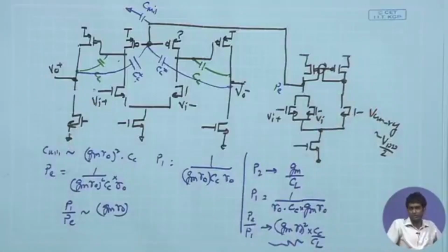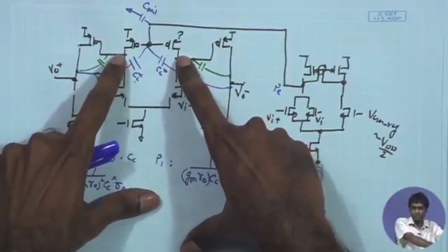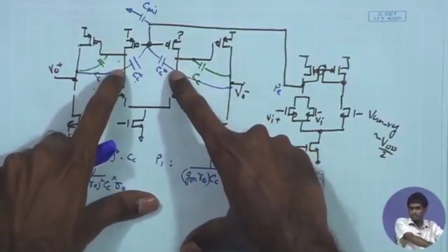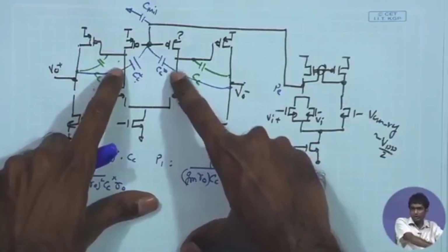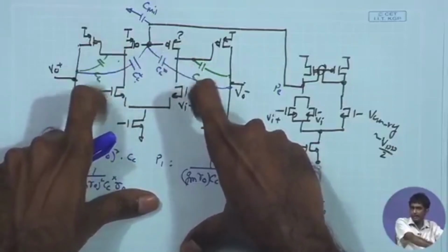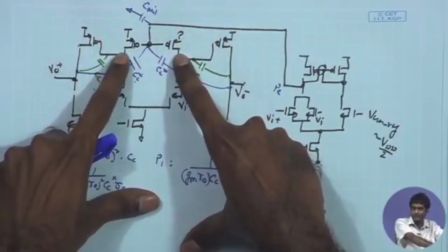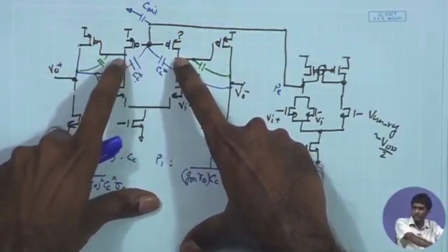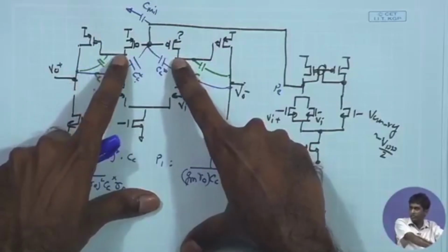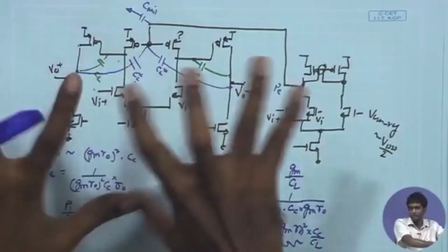And there one of the other issues is that you do not have a very fine control over this. This can end up being too low also, or too high also, and therefore the transistor over here can end up in triode more easily. Whereas when you are defining this at a desired point, say equal to VGP, then it is much more ensured, or you are having an appropriate DC point over here. So that is another advantage of using dual loops.